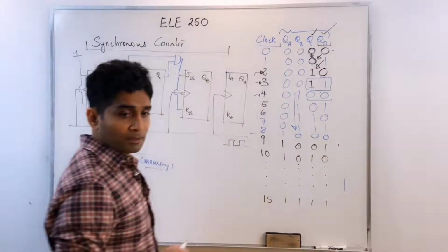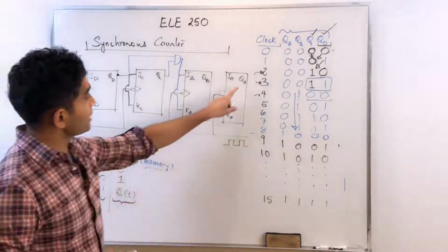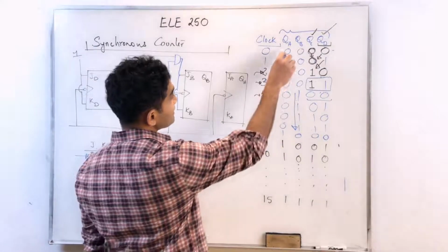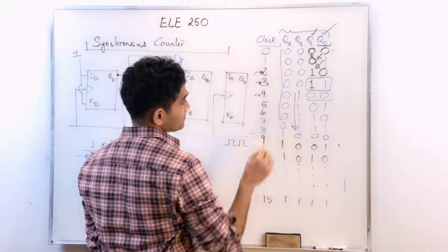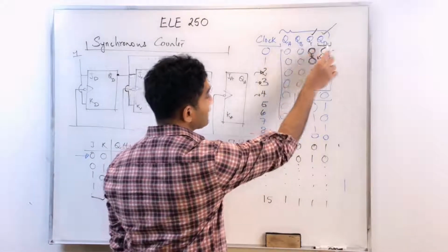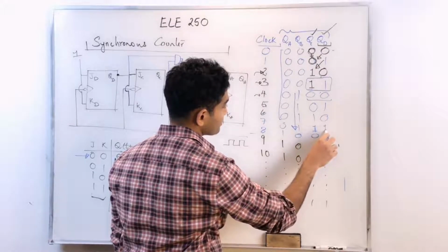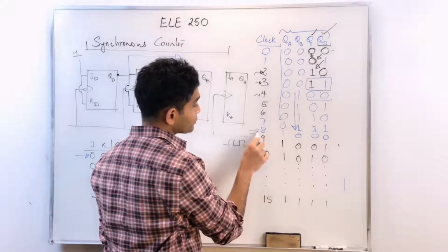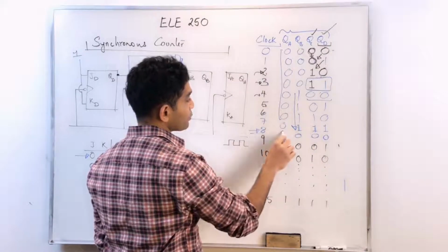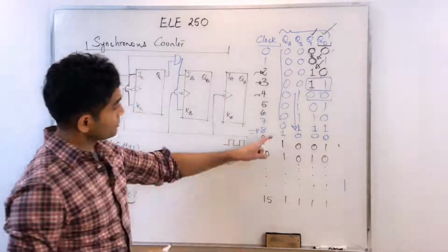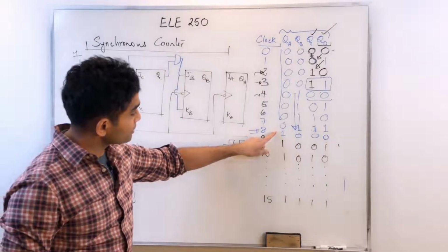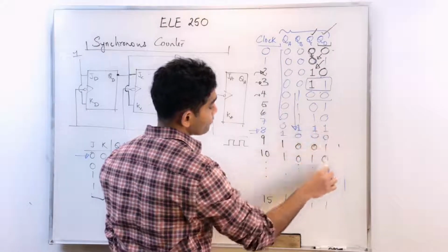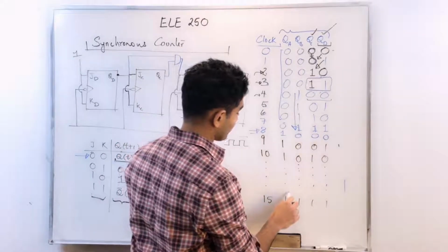Okay. Now, what about JA? What about the J and KA flip-flop? The response, again, has to be in the memory state until when? Until my QB, QC, and QD are all ones. When they're all ones, in the next active edge, my QA should toggle. And then it remains 1 until my QB, QC, and QD become 1 again, which happens where? Here somewhere, right?